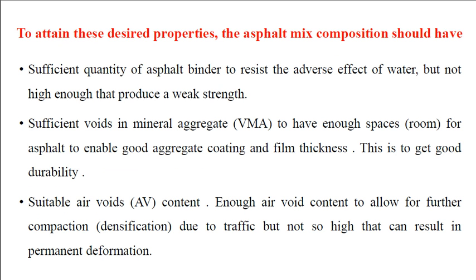Next, in order to attain these desired properties, the asphalt mix composition should have a sufficient quantity of asphalt binder to resist the adverse effect of water, but not high enough to produce weak strength. Then sufficient voids in the mineral aggregates in order to have enough room for the asphalt to enable good aggregate coating and film thickness. So this is to get good durability. Next, suitable air voids content, enough air void content to allow for further compaction, that is the densification due to the traffic, but not so high that it can result in permanent deformation.